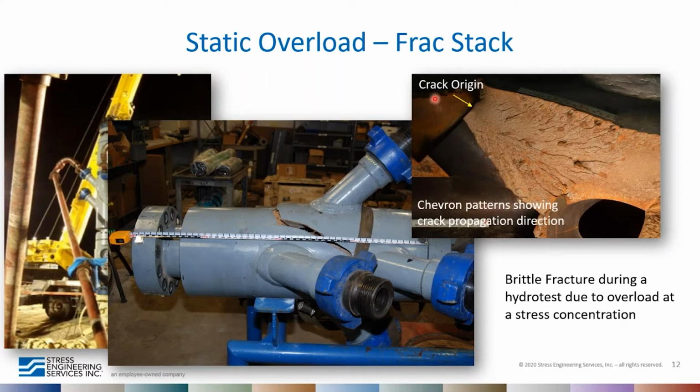And when we take a look at the fracture surface, we see that there's a crack origin and chevron patterns which point in the direction of the crack propagation. Okay.